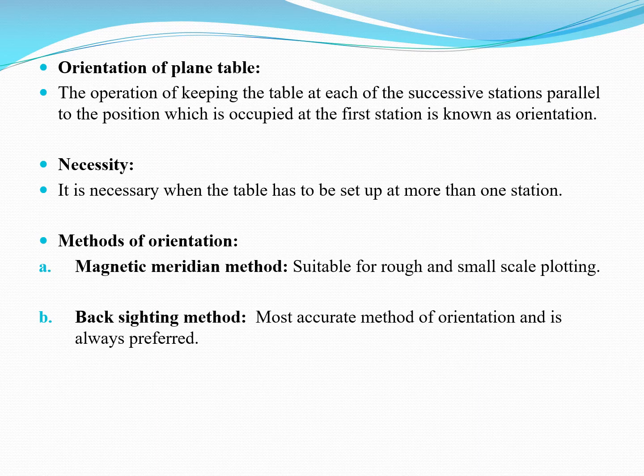After that, the plane table is turned clockwise or anti-clockwise until the needle shows exactly the north-south direction, without disturbing the centering and leveling operations.